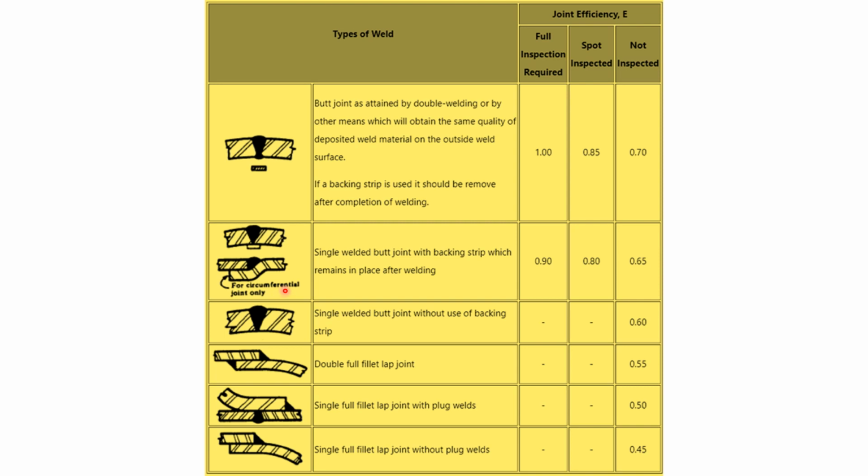This is not applicable for a long seam joint. That is, when you roll the shell, it is not applicable for the long seam, but for the circumferential joint it is applicable. Okay. So type 3, it is single welded. In the back strip there is no welding done, or this back strip is not used at all. This is type 3. And type 4, the double lap joint.